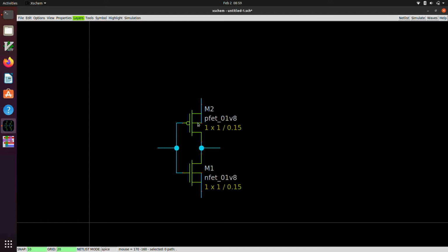The problem that could potentially arise is that if you forget to connect power up, especially in the layout, that can create a real problem, because if you use global net labels in Magic to connect things up, and then at the last stage when you do your layout you happen to forget to connect the well up someplace with an actual metal connection, you'll have a floating well and your chip may not work because of that. Very likely it will exhibit strange behavior that you did not intend at the very least.